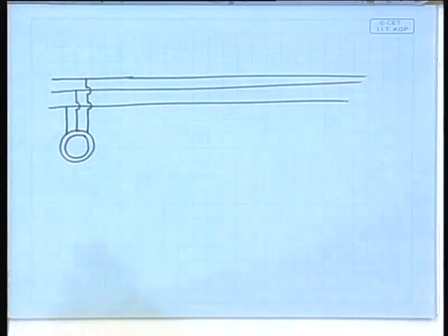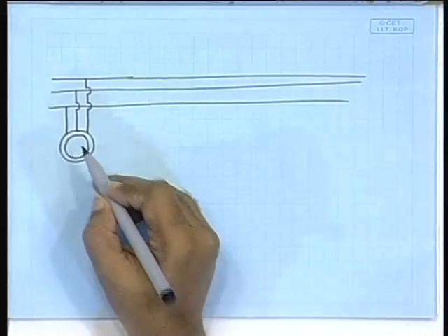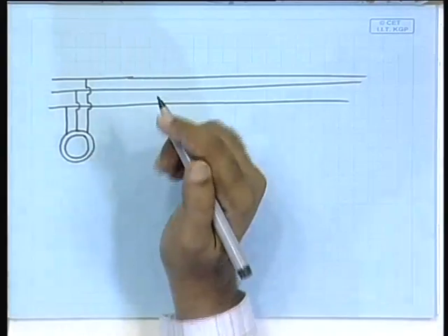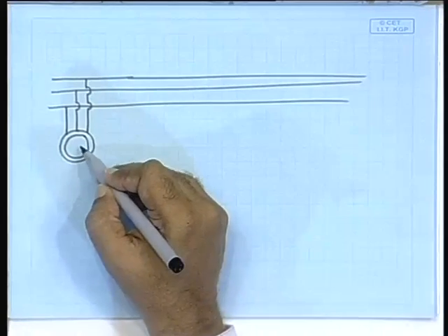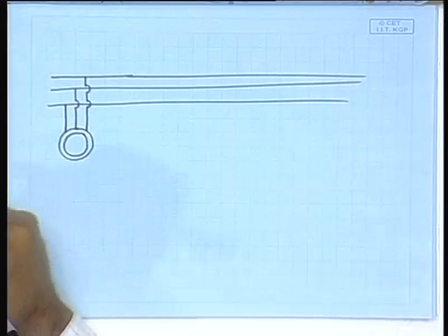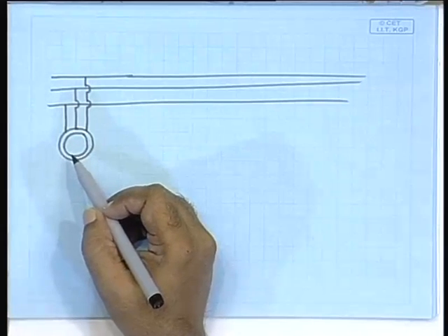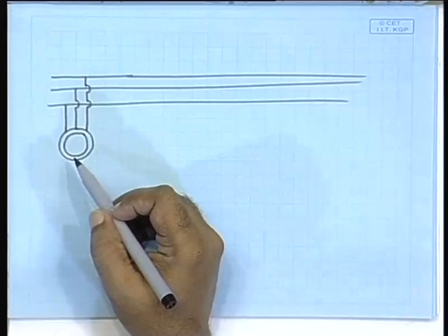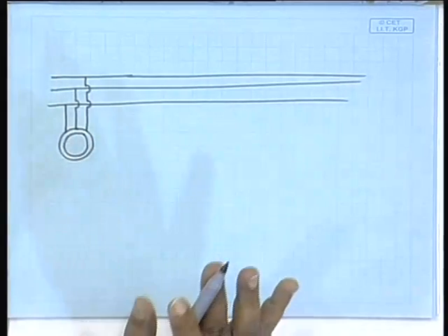So far you have learnt that this rotor, as it is rotated, if the speed of rotation is bigger than the synchronous speed, then it will generate power, and that is what will be pushed into the grid. But then that can go on only till you have reached the rated speed. That means it is then pushing out a rated value of the power.